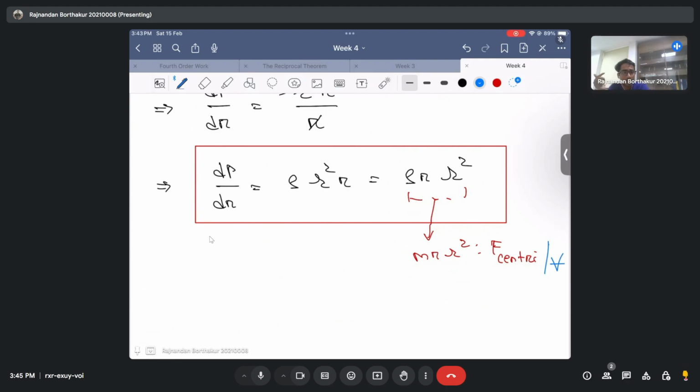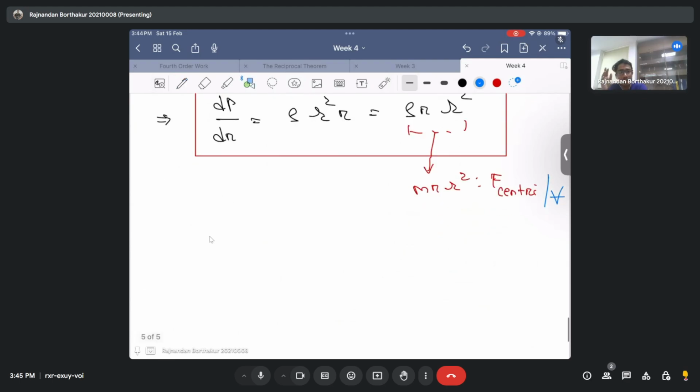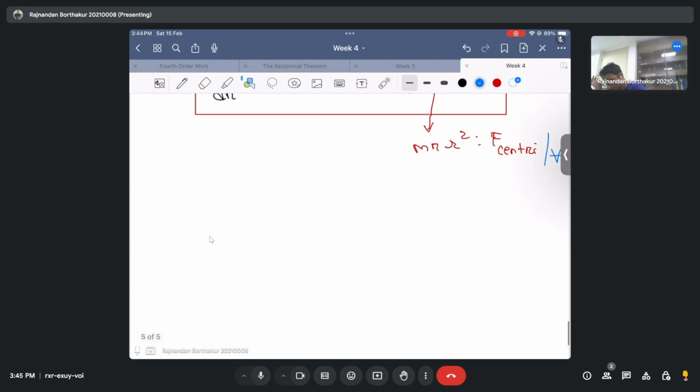But what we saw is that the pressure gradient in the r direction, if there is a rigid body motion, is being balanced by the centrifugal force. That is something that you must realize. And what does this actually mean? This means that if I now draw the streamlines, for instance for case 2, where there is no inner cylinder and the outer cylinder is just rotating with some omega, how would the streamlines look like?